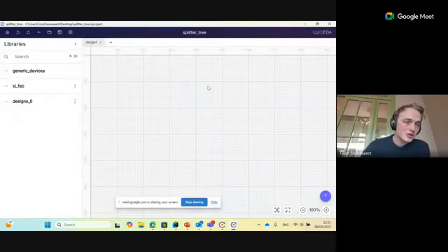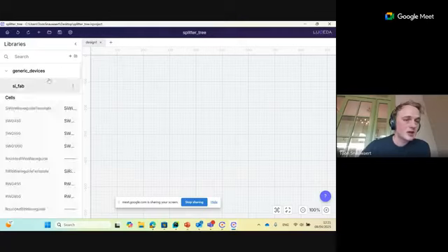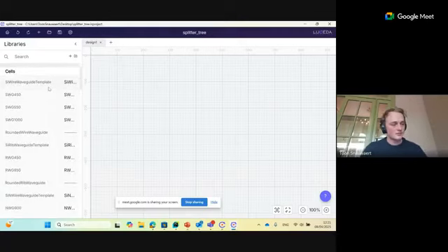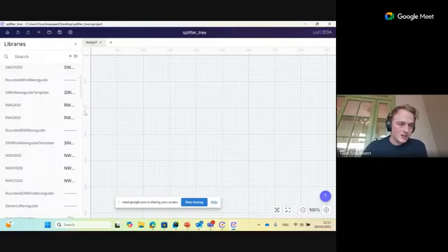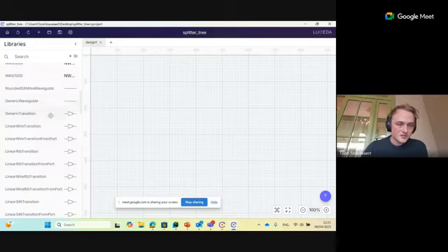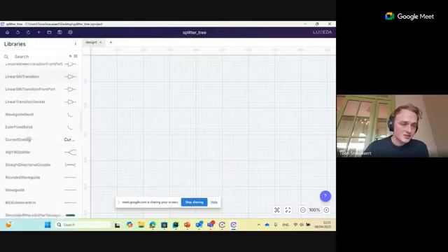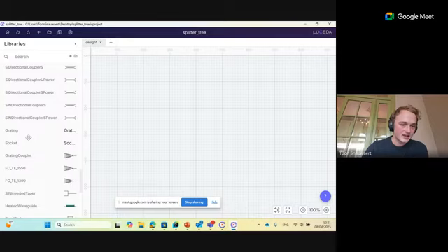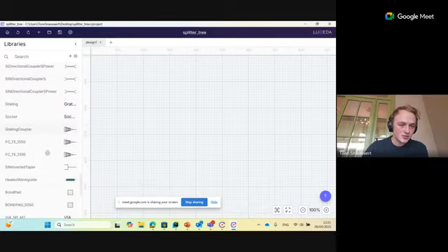Now in Canvas, we have our library of SciFab. Inside this library, you can see all the predefined components of Silicon Fab, which is our PDK that we use for demonstrational purposes. What we can do is take these components and just drag and drop them.